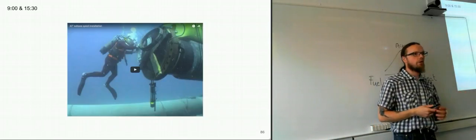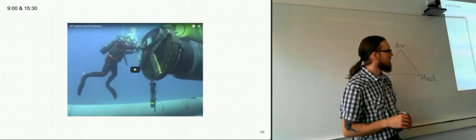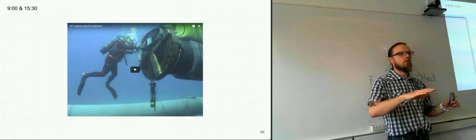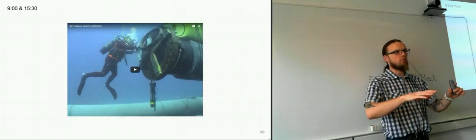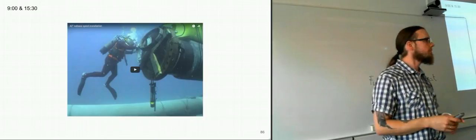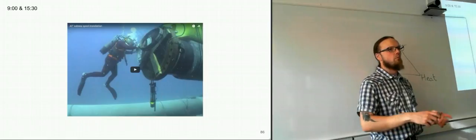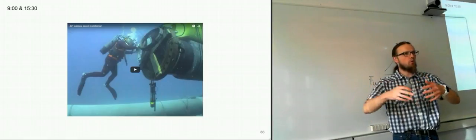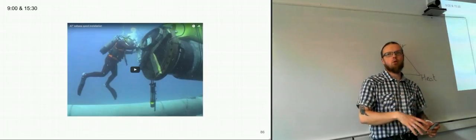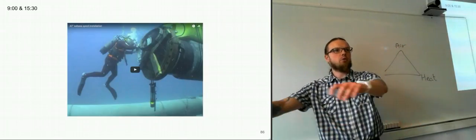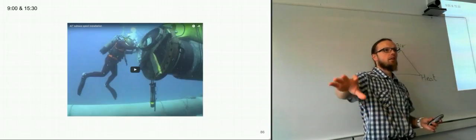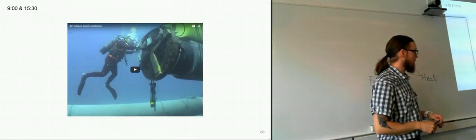And that's also something ROV pilots do: they try to keep their movements fairly slow and purposeful, so that they avoid sudden movements and don't swirl the water too much. Which also means that while they're moving around the area where they're working, they are not going full speed from one place to another, because they know there's going to be a cloud of swirled up sediments that's going to follow them. So they try to just glide pretty slowly over there.